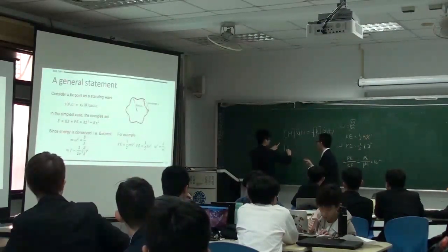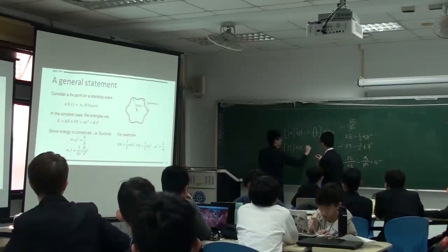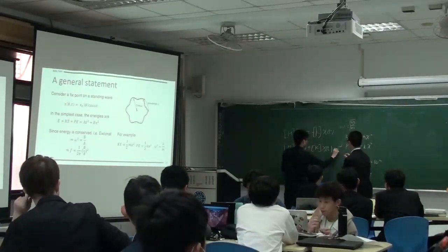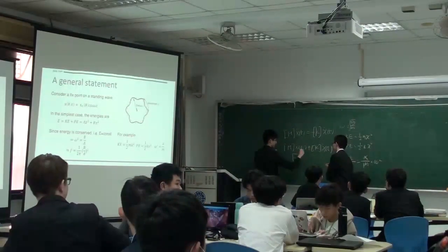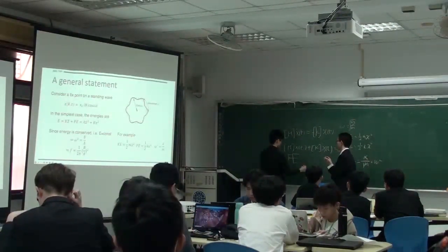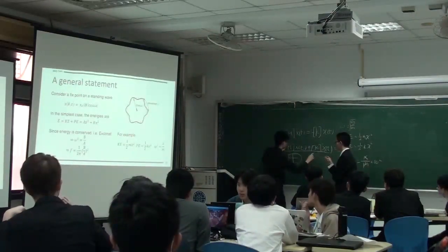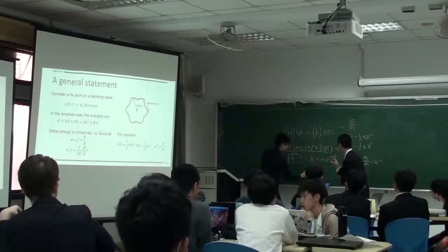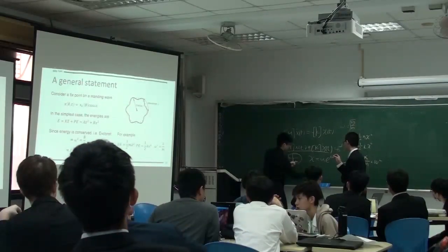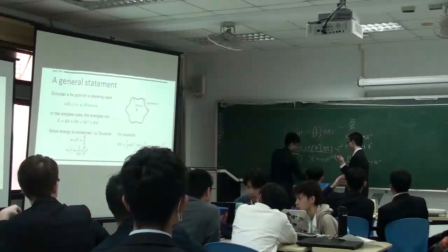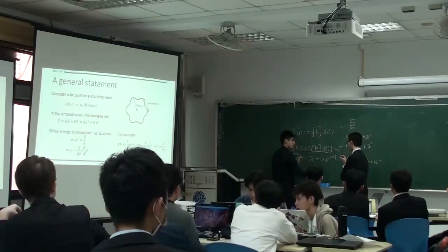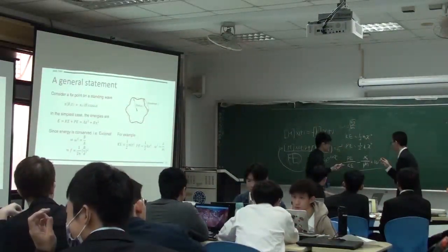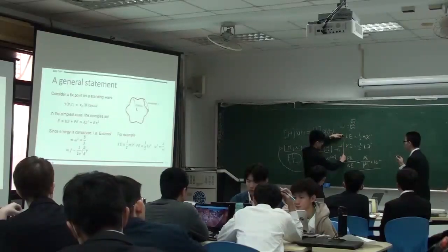So you can have this equation, where K and M are matrices, and through the finite element method you can know that the x here can be written in this form, and that omega squared actually has something to do with its eigenvalue. You know what an eigenvalue is? Okay, so it has something to do with the eigenvalue. So if you use this equation, you derive it in this way.